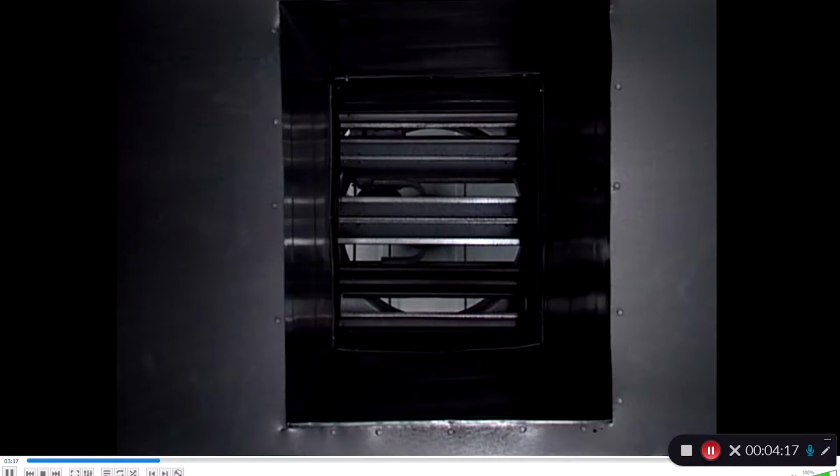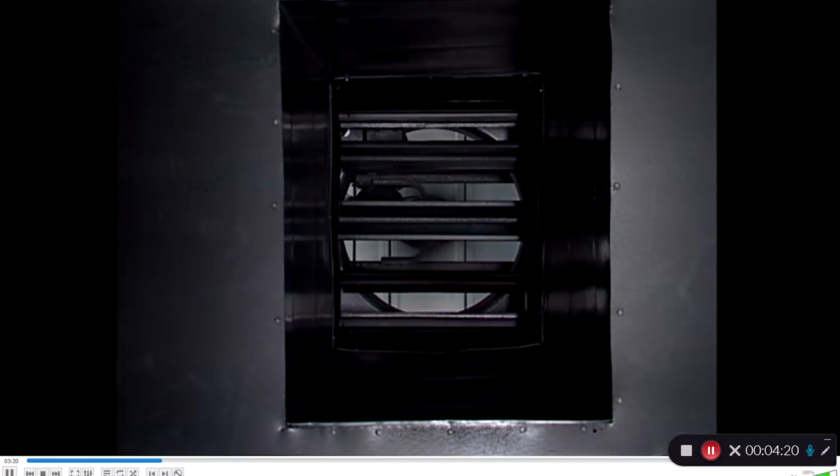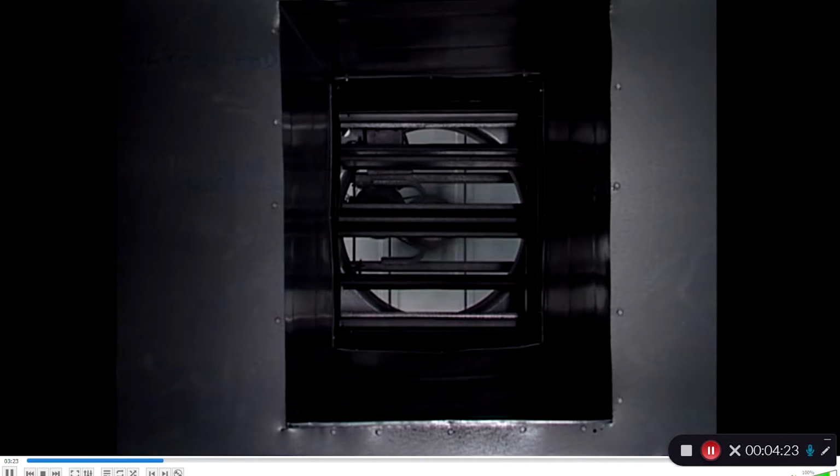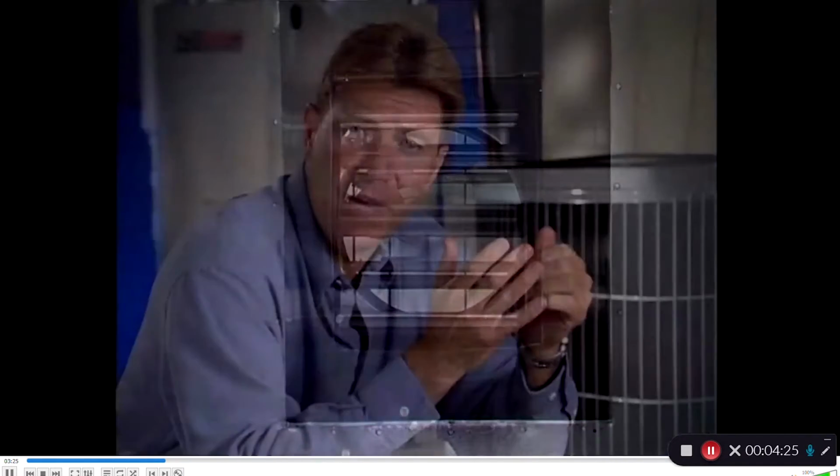By increasing the amount of outside air brought into the structure, the concentration of air contaminants and pollutants can be reduced. If air is brought into the structure, an equal amount of air must be removed in order to prevent pressurizing the interior of the space. Indoor air quality can be improved when proper ventilation procedures occur. Commercial buildings are often designed with mechanical ventilation. Ventilation has a negative effect on heating and cooling efficiencies, as the air that is brought in from the outside must be heated or cooled to maintain the desired comfort level.